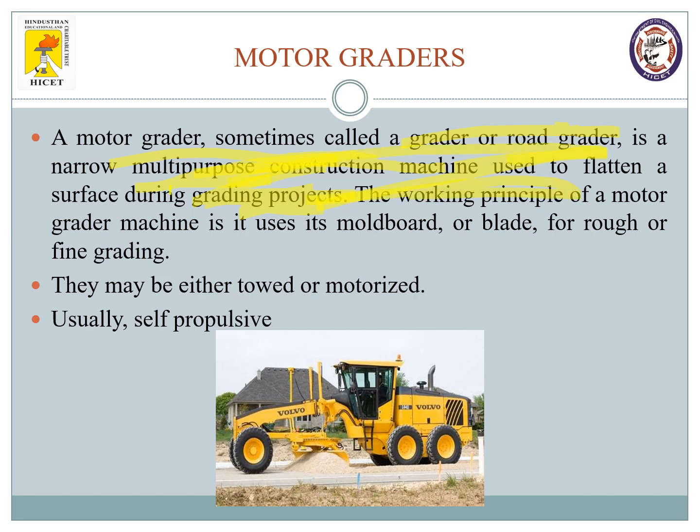The working principle is very simple. It uses a mold blade, or a blade, for rough or fine grading. Here, if you are able to see, there is one blade. It is going to level your soil here, right? The earthwork will be leveled here. This may be towed or motorized. You can use it along with the tractor and tow it, or it can be motorized. Usually it will be a self-propelled machine, because if it is self-propelled, the output efficiency will be very good. So motor graders are generally used in highways for flattening any surface in transportation engineering.